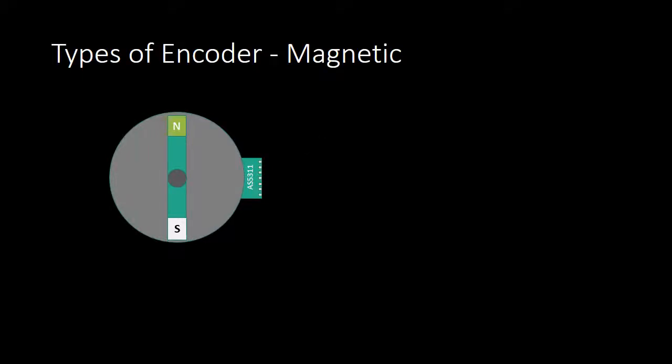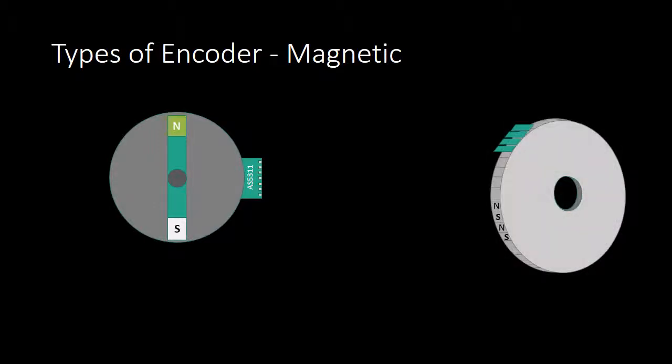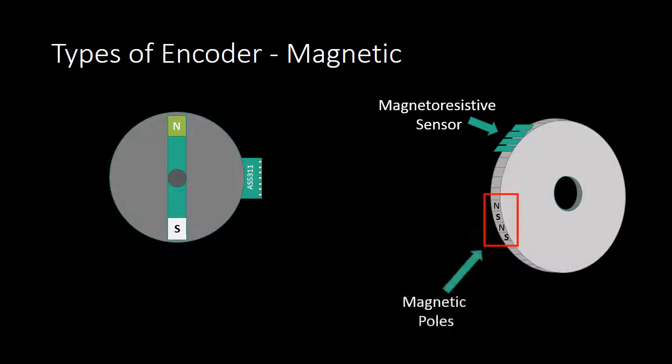For high-end encoders, higher resolution is expected than Hall effect sensors can deliver, and magnetoresistive sensors differ from Hall effect sensors in two important ways. The saturating field is much smaller, which makes magnetoresistive a much more sensitive measuring device, and the change in resistance is independent of the magnetic polarity. So a 32-pole wheel generates 32 pulses per revolution, twice the resolution of Hall effect sensors.